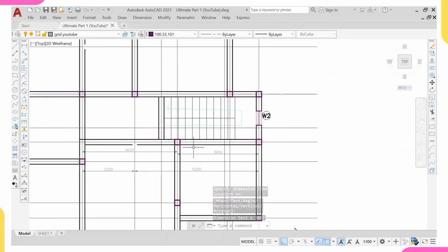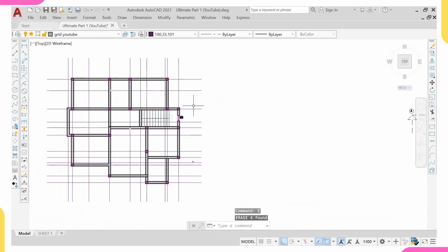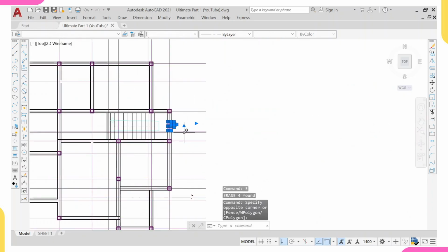And two, this one is not really carrying a point load, it is just carrying a small load from a small slab. So for me, this is okay instead of having a column placed here. These are part of the things you as a structural engineer need to take into consideration while doing your structural framing. So right now we are through with everything concerning our structural framing.